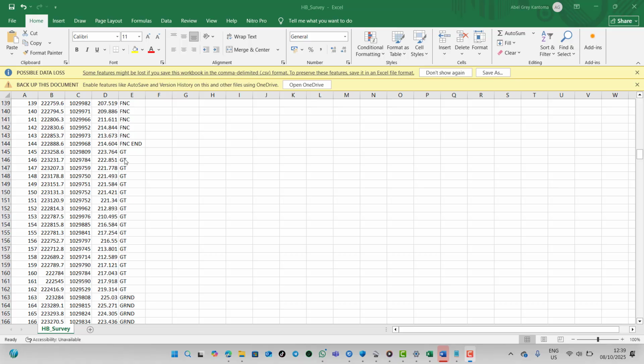It shouldn't be more than 6% when it comes to the grade along this gate area that you are seeing. And then you should not go more than 500 mm either below or above this gate level. Any of these gates shouldn't go below or above. These are very key, important pieces of information.